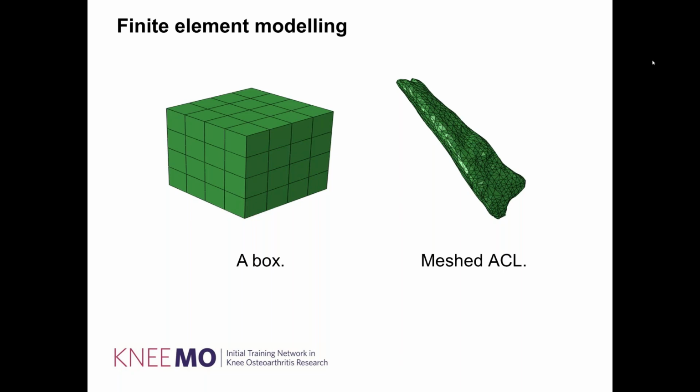It doesn't predict the actual loads that the cartilage goes through. And even though you get actual compressive forces from the musculoskeletal stuff, that doesn't take into account the geometry of the knee. So, for example, if you have a huge load but it's distributed differently over a wider area, then you also get lower stresses, and that doesn't really tell you what the cartilage is going through. So that's why we need finite element modeling.